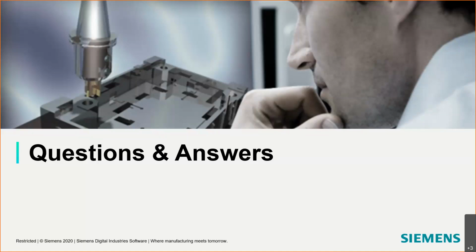You're absolutely right there, Steph. I was thinking more about using the out of the box tools, but from a tooling library, yes. So if you want to use your own tooling, you would need to define it before. Feature-based machining will not create tools for you because it can create any tool in any radius, diameter and length, and that's probably not what you want.